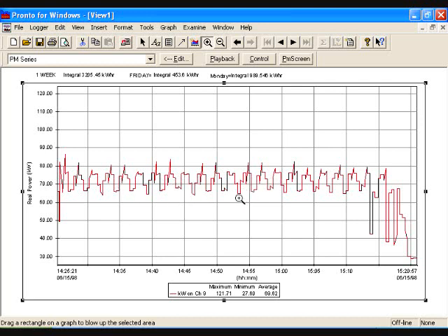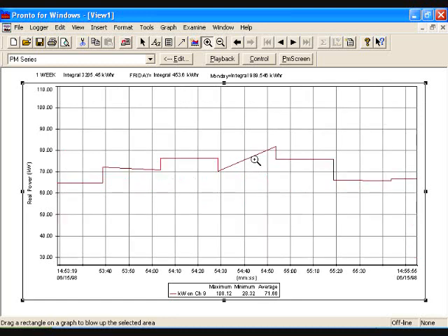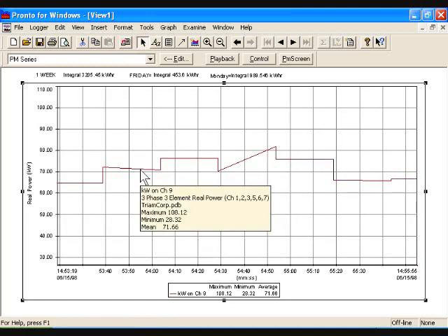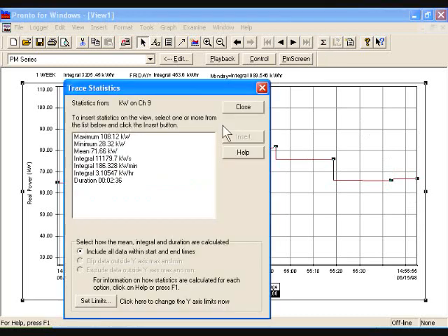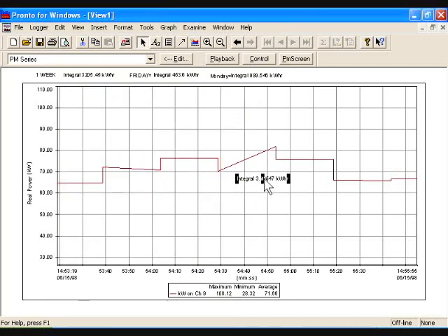So what we want to do is just zoom in on one single part being made. One cycle of the machine, in other words, of the manufacturing process. Now, this is one part we're looking at here. If we now click on one part, we put the handles on the one part. Now we go to the Greek letter sigma and the kilowatt hours used. You can actually see, we click on that and we insert it. This is the amount of power required to make a single part.